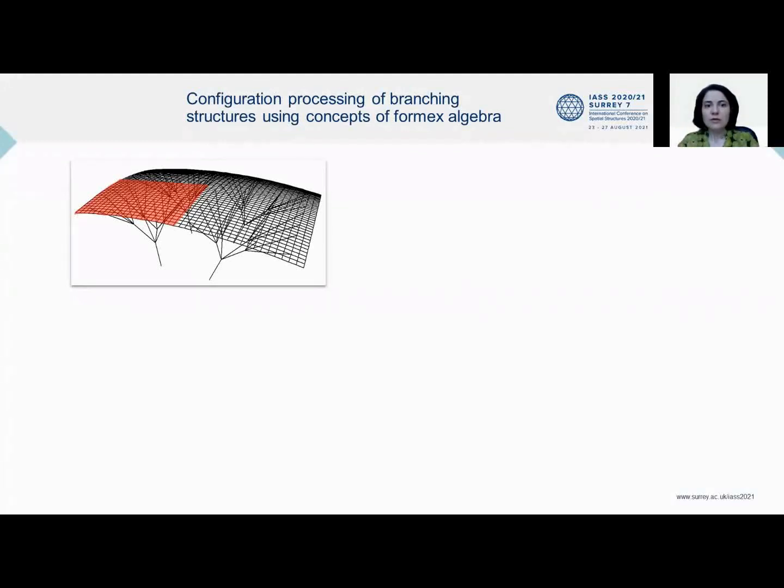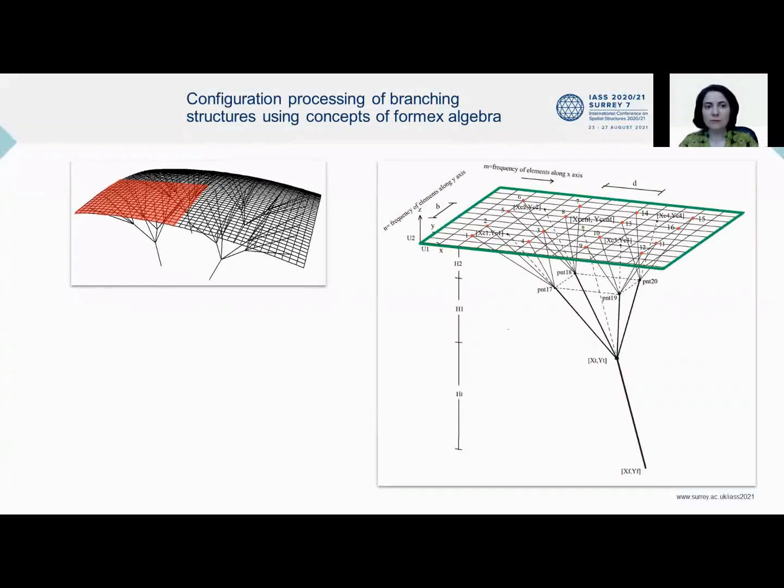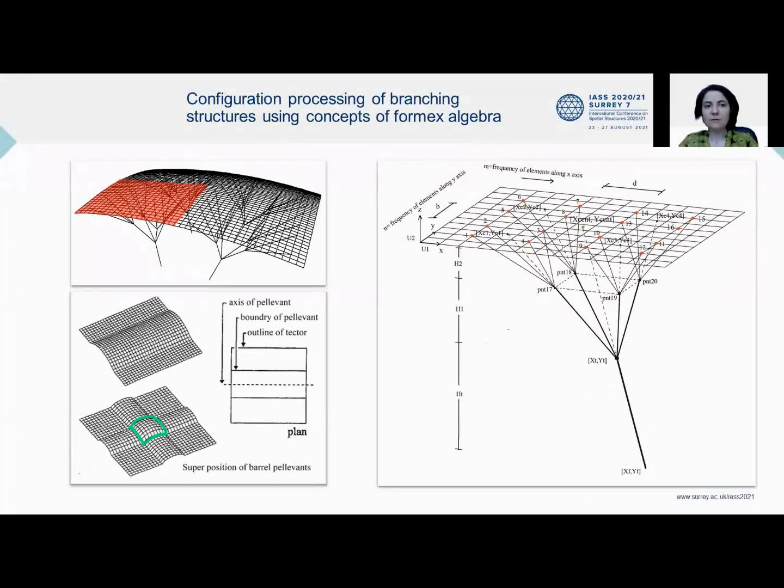The configuration processing of branching columns begins with a parametric model of a flat grid shell, the centroid of a quarter of the grid, the knots where the branching columns touch the grid, and the relevant centroid of each set of 4 second level of branches. Then the flat grid shell and essential points are projected onto a curved surface by applying the circular barrel elevation function twice.